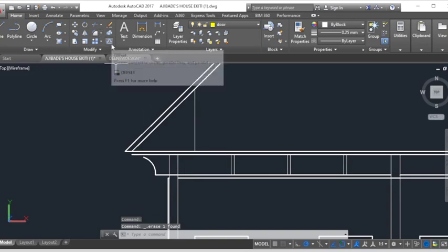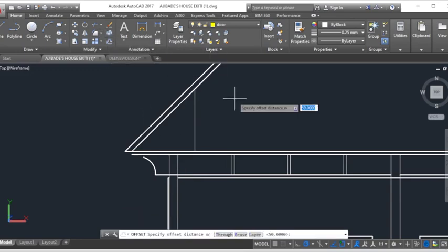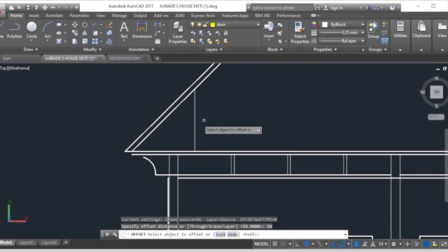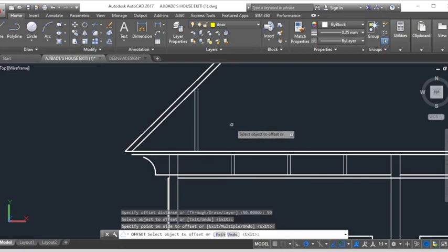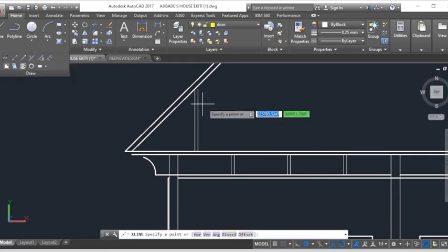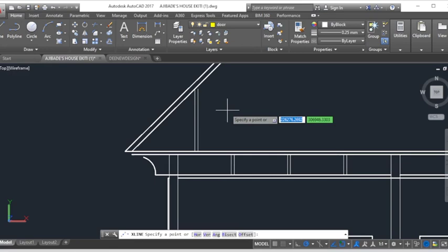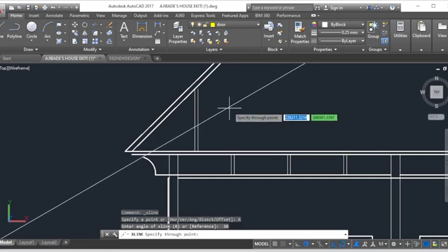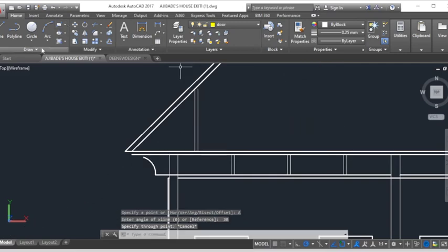So I would go to my offset, I set 50, then enter, from here to here. So what I need is construction line still. Construction line, this time around I need angle line, so I'll use A, enter. Let me try angle 30 and see how that looks like. Nope, angle 30 is, okay, sorry, that will be minus. Let me try 45.